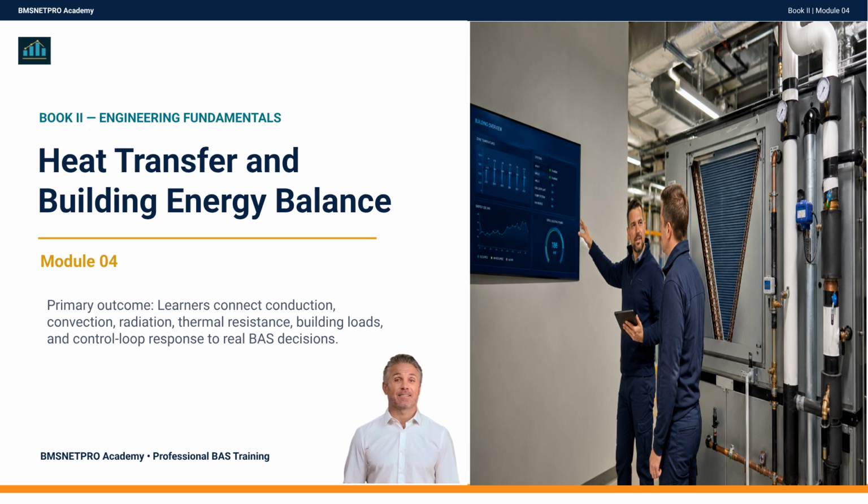The BAS does not directly command comfort. It commands equipment. It opens valves. It moves dampers. It changes fan speed. It starts pumps. But the building only responds when heat moves through air, water, walls, glass, coils, and building mass.